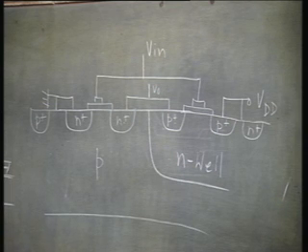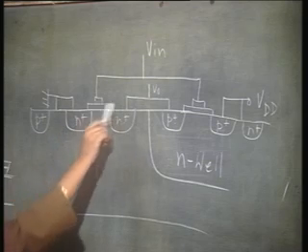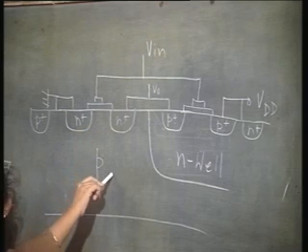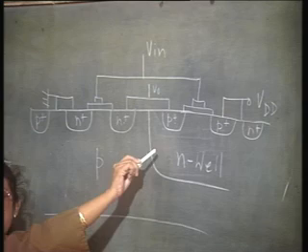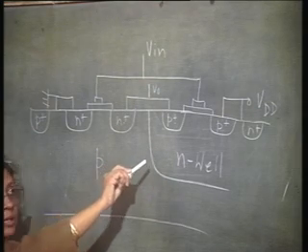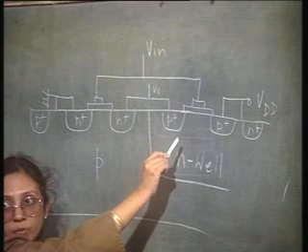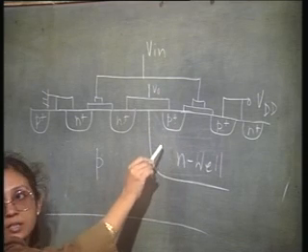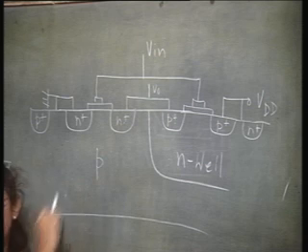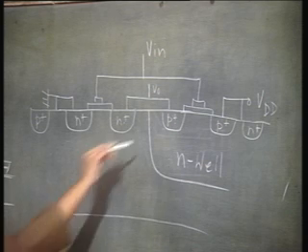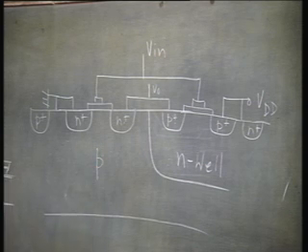Now, the problem is that once the noise spike has occurred, which is sufficient to turn on this junction, there is a flow of electrons, and in that process there is a sufficient potential drop, so that this junction again gets forward biased and keeps injecting holes here.